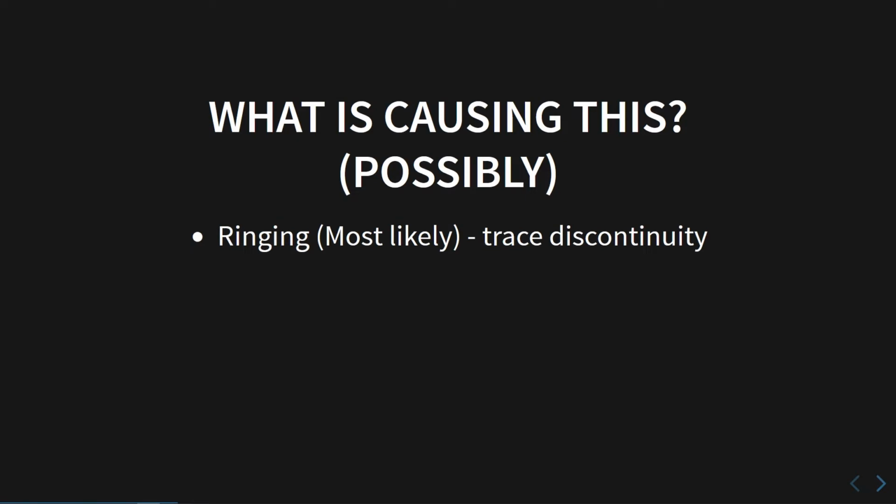But what I've realized might happen is something called ringing. Ringing would happen when there's trace discontinuity. In simple English, if I have a wire and there is a change in impedance, that would cause some form of discontinuity, because the signal is constantly looking at the impedance, the voltage divided by current, at that very specific instant. If that changes, it's going to cause something called ringing or reflections. And if there's too much ringing or too much reflection, it can create a false trigger of a MOSFET.